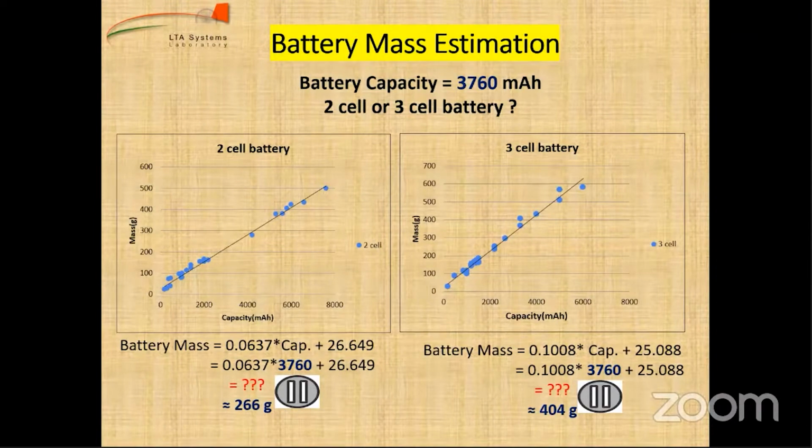Let me give you some facts to give you a little more perspective. If you remember the previous sessions, we had calculated the mass of the fins, gondola, and envelope, right? So I'll put those numbers in front of you. The fins were 126 grams, the gondola 65, and the envelope 579 grams, right? They're the same order of magnitude. In fact, the percentage differences are significant, right? If there's such a huge difference, it really means a lot for the airship.